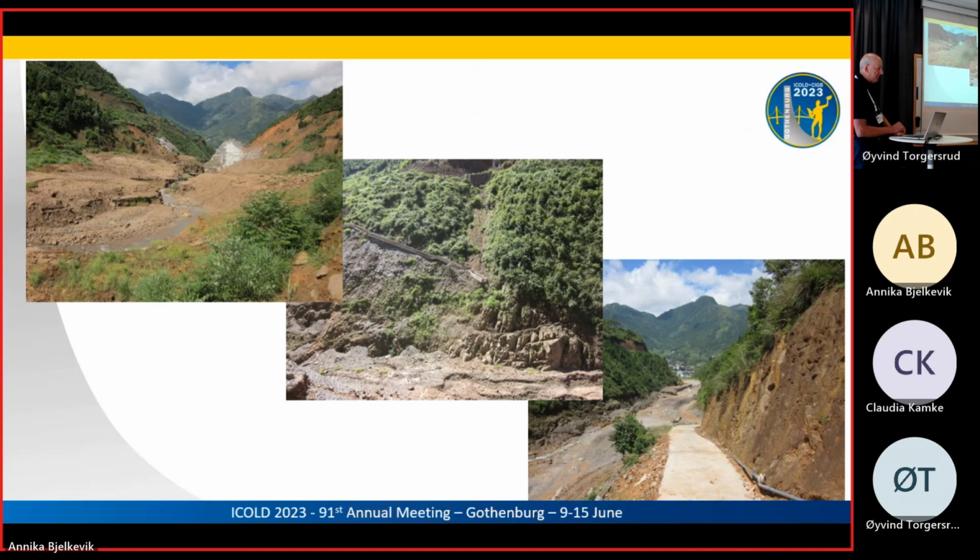But unfortunately, they had something like a 1 in 200 year event, and there was a lot of erosion. You can see the steep countryside around with fairly bushy vegetation. A lot of that vegetation got washed off, floated around in the dam and blocked off the screens that led to these spillways, and so the water level rose.